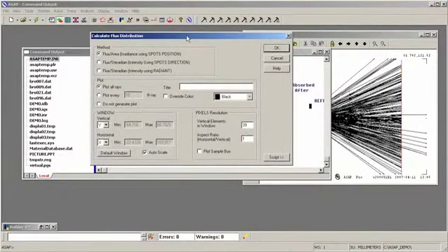This dialog box allows the user to calculate both irradiance and intensity. Irradiance is the default, so I won't change that setting. Down here, the window axes, vertical Y is okay, horizontal will be Z, and finally pixel resolution for the irradiance calculation. In other words, how many pixels are aligned along the vertical axis of the window.